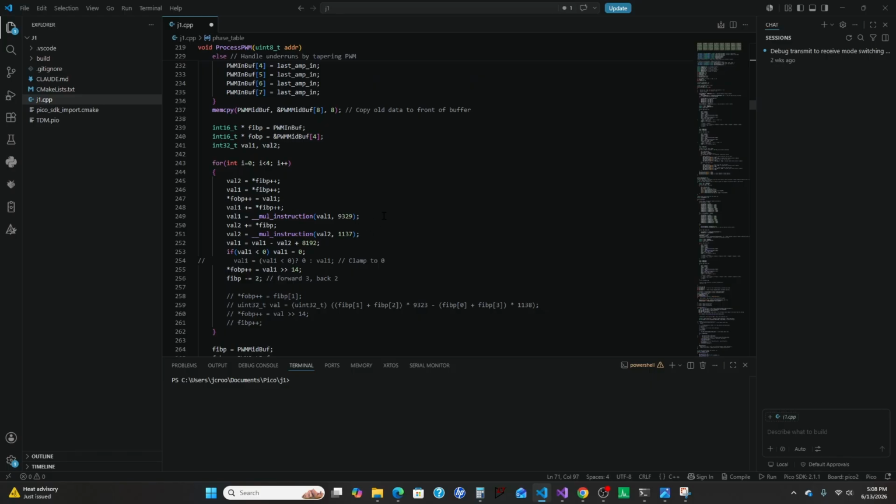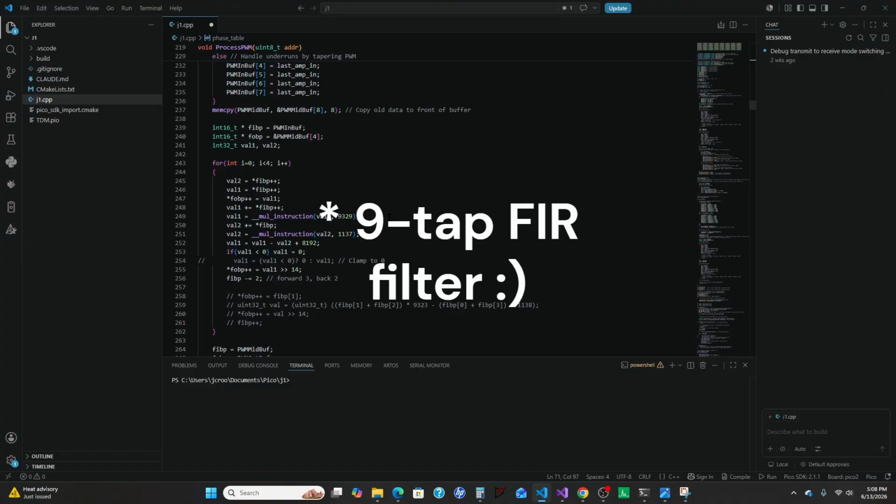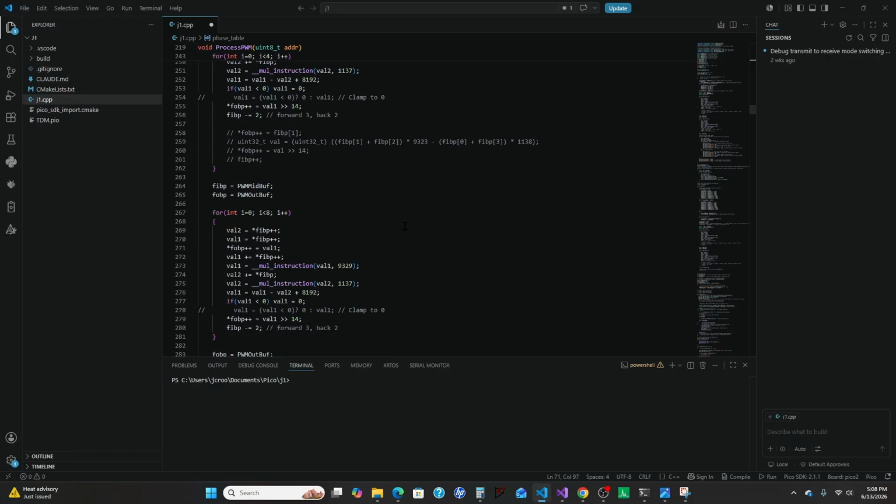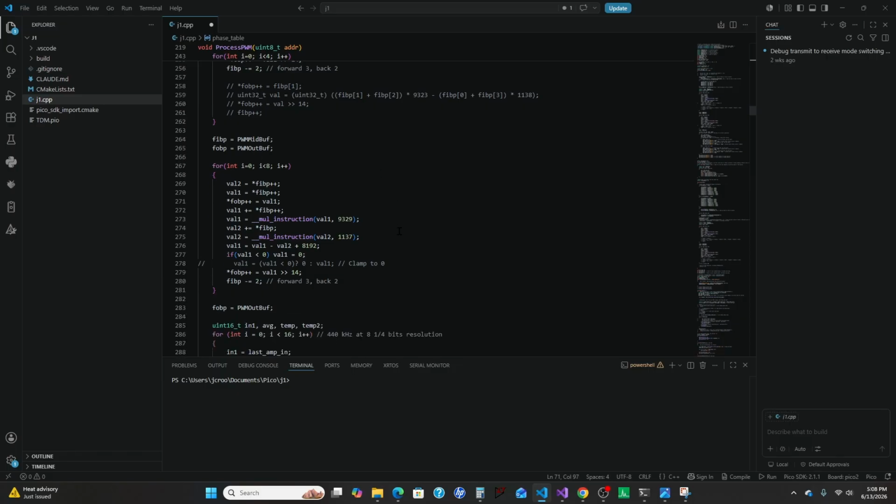You can see the 2 multiplies I mentioned. This ends up being an 11 tap FIR with as little math as I could squeeze in. There might be a better way to do it, but I think this is about as close as I could get. And then of course we've doubled the number of samples, so then we have to run the next FIR filter over twice as many samples.